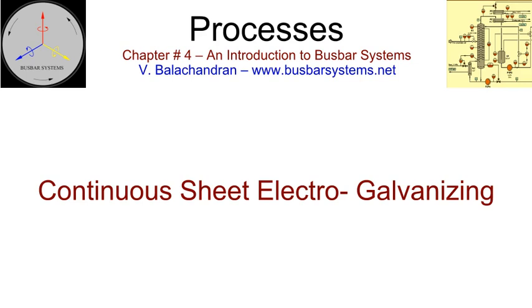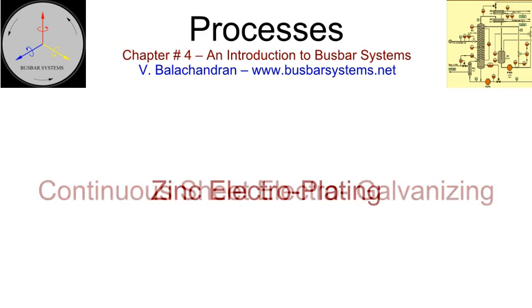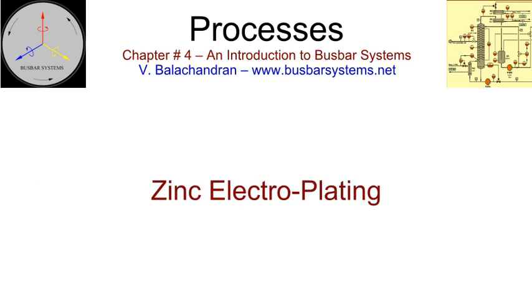In general, the thickness of the deposit in the electrogalvanizing process is less, and therefore not recommended for outdoor use without supplementary coating. Zinc electroplating. Zinc plating is also an electrodeposition process but is carried out on small components such as fasteners, washers, etc. The components are subjected to degreasing, pickling, and rinsing before being loaded into a drum. The drum is immersed into a plating solution and rotated for uniform deposition of zinc.